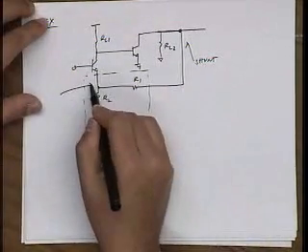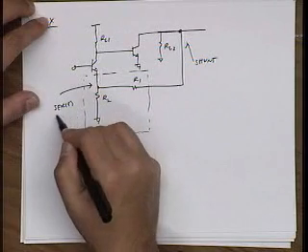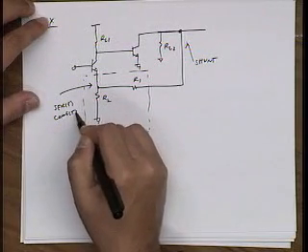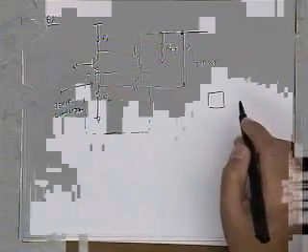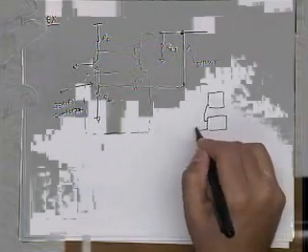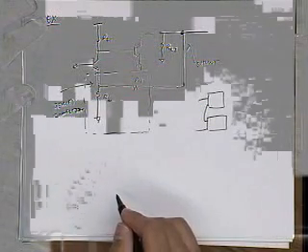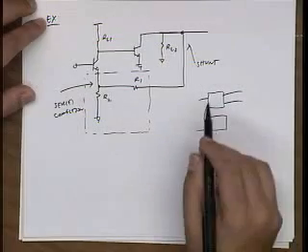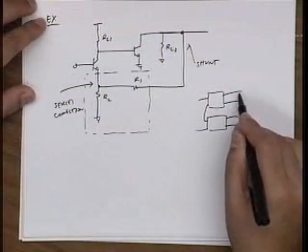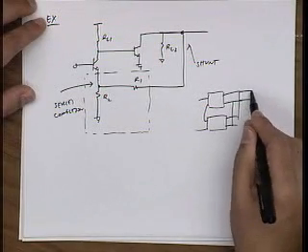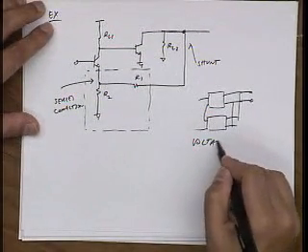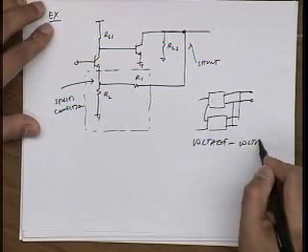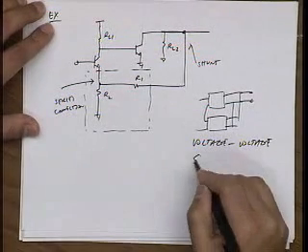And then this is a series connection. So I'm subtracting out a voltage on the input. So series on the input, right? If you forget, just draw this picture. Series on the input is voltage subtraction. Shunt on the output is a voltage connection. So this is actually a voltage-voltage connection. Or series shunt.